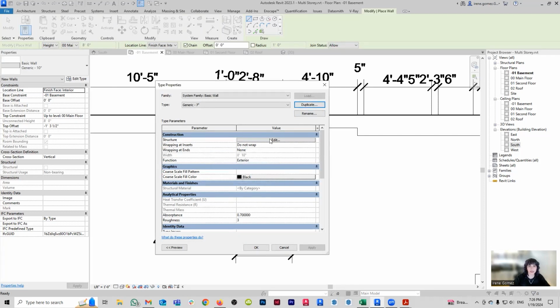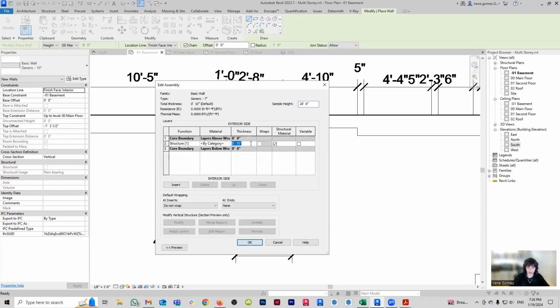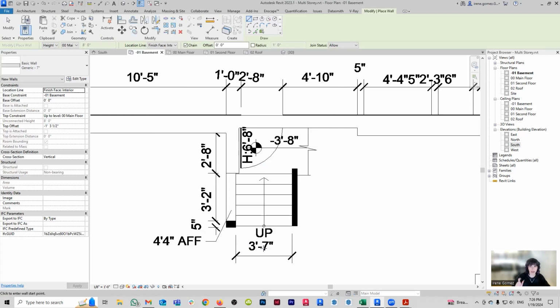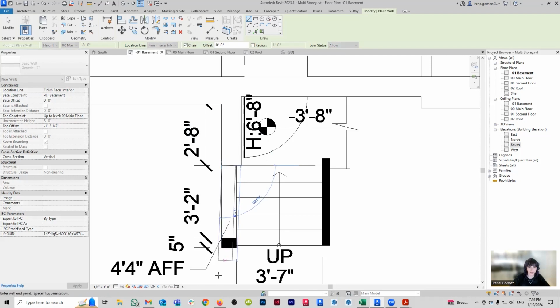This is one of the reasons that I recommend doing separate finished walls as a type that just gets layered in front of architectural walls. You can see how many types of architectural walls you can have just based on the thickness within a single project. If you have to add on top all of the different finish variations that you may have within a project, you're going to go insane if you try to have one for each variation. It's just not really feasible.